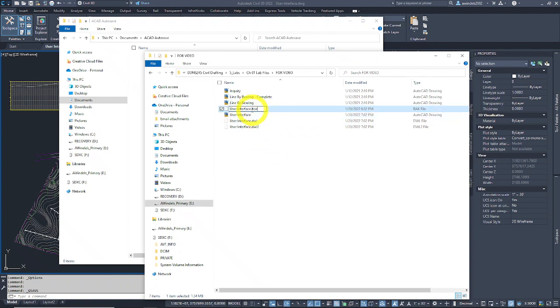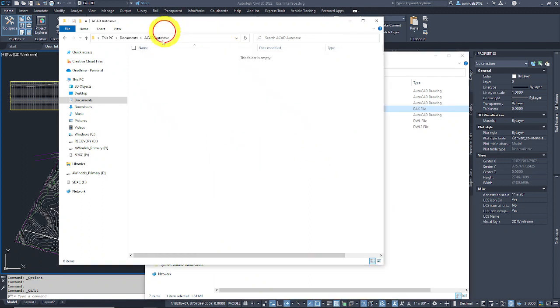They're called this. This is the last save of your file. If you want it to function, say like this file, your main DWG, you have to physically rename it to DWG to get the functionality of the drawing. It won't like that because I've got two of them, but that's what you have to do. Same with the autosave files that populate here. You need to rename them to DWG to make them usable.